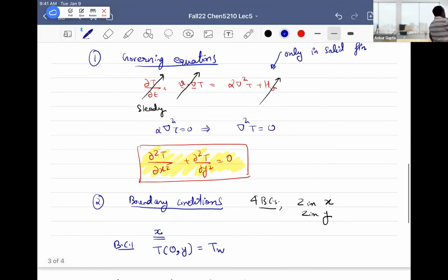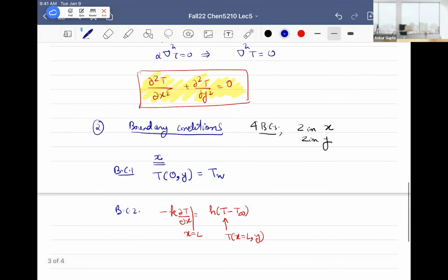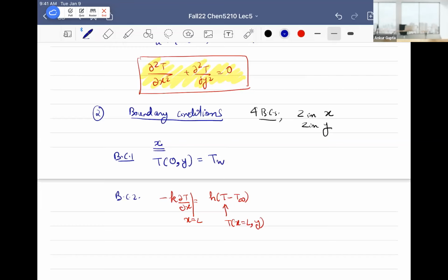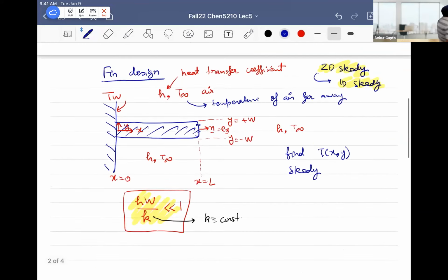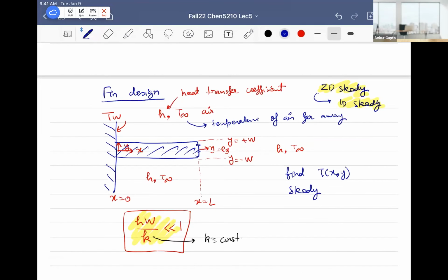This was the question that came up last time, and one of the students asked me, and I never thought about it: why didn't I take T infinity minus T? Why did I take T minus T infinity? How do I decide this? That goes by the direction of the normal. Because my normal is in this direction, equal to e_x, I go in the direction of the normal, taking the temperature first at T and then at T infinity. Hopefully this will become clearer as we keep going.